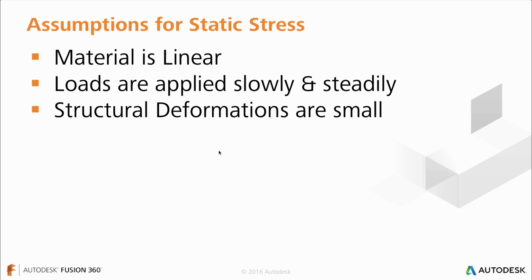So if you think about different loading methods, one could be just the force that gravity plays on your model, and that would be a very, very slowly applied force. I don't know if you could even really consider it being applied, but the way that the software is going to apply it is very, very slowly. A force, let me use a different example. Gravity wasn't a good example. So if you push on something like a cantilever beam, you put a force on the end of it, and you do it slowly, it's going to behave differently than if you were to apply the same exact force but with an impact. So impact loading is more of a dynamic study, and the mathematics is different. The approach is different, and you'll get very different results if you apply the same force slowly versus if you were to apply it dynamically or with an impact. The other assumption for static stress is that structural deformations are small.